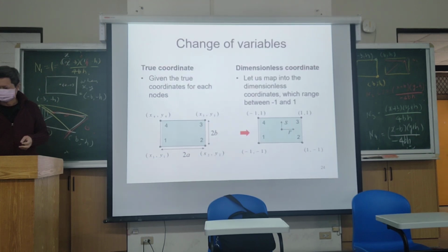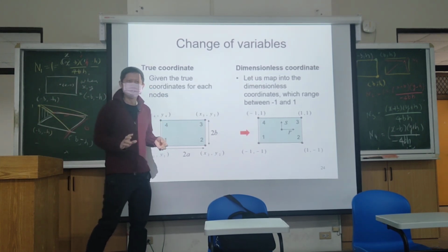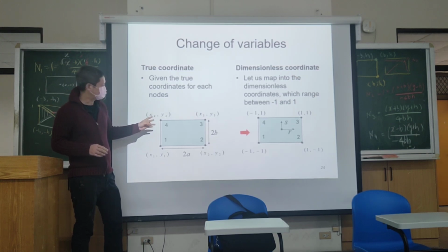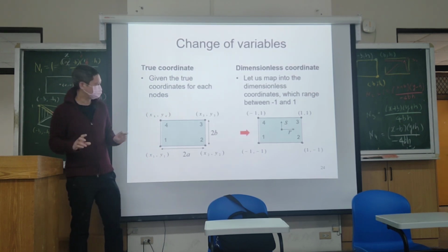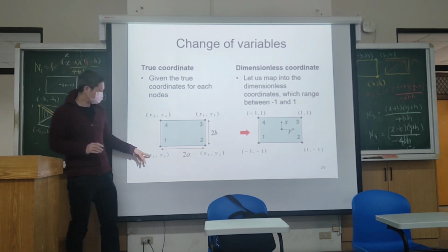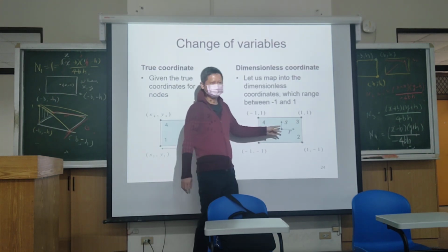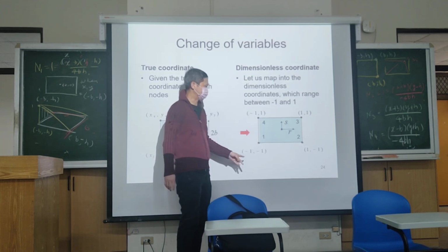Okay. So next, come back. Why do you need to use the mapping? To do the mapping, the reason is I'm not going to just handle the 2D rectangular element. I'm going to handle the 2D quadrilateral element. So this matrix now, rather than using the physical coordinate, I'm using natural coordinates R and S. R in the X direction and S in the Y direction.